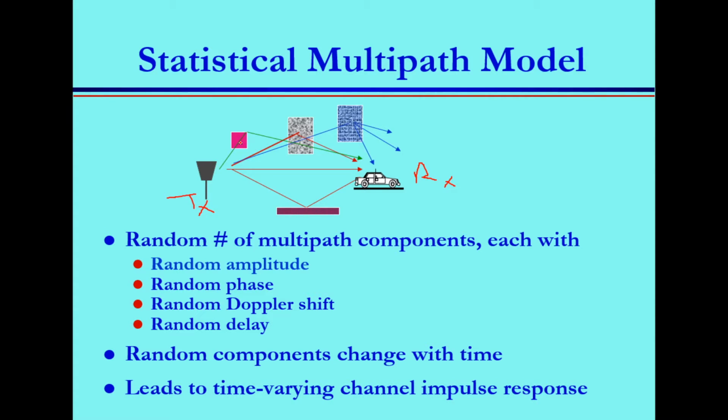Random Doppler shift: the shift here, how much spreading you have from the original frequency. You transmit over f equal 800 megahertz. At the receiver, this should be received at 800 megahertz because your receiver is synchronized at that frequency. Now, sometimes due to Doppler spread, you receive your signal at 810 mega. You have spreading. What's the reason of that? Your signal gets reflected off a mobile object, like a car, like a train, like a plane, anything that's mobile. When your signal hits and gets reflected, it changes the frequency.